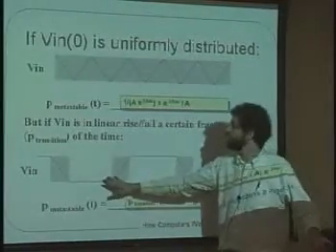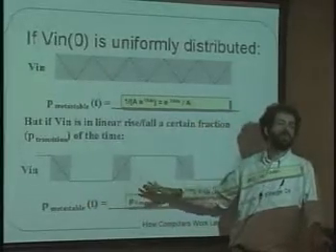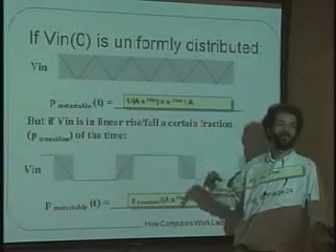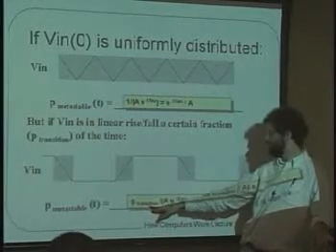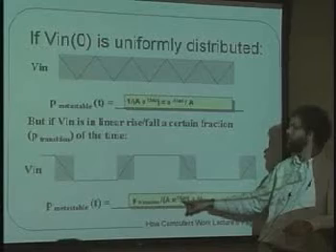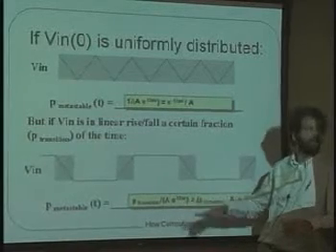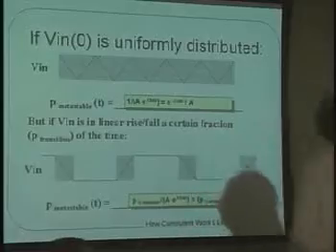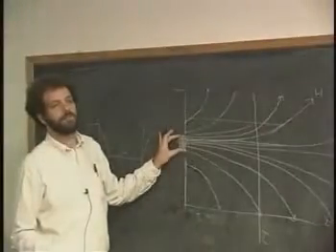So if 80% of the time you're not in transition, then only 20% of the time do you have a probability of being metastable. So that's why you multiply by the probability that you're in transition. And then you also have this a e to the t over tau, which has to do with what the probability is based on exactly how big this part of the curve is.